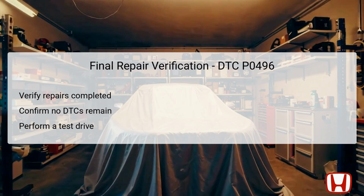After repairs have been performed on the EVAP system, it's essential to conduct a final verification to ensure the issues have been resolved. Start by inspecting that all repairs have been thoroughly completed and that no diagnostic trouble codes, DTCs, remain active.